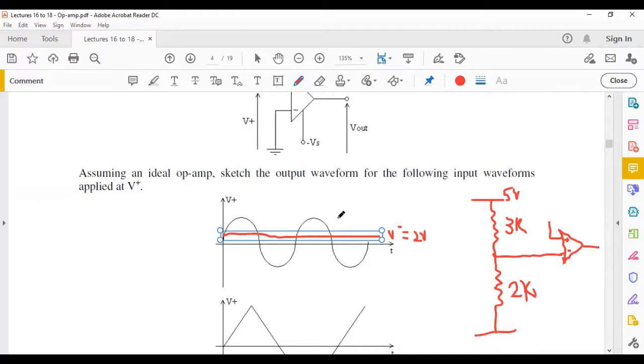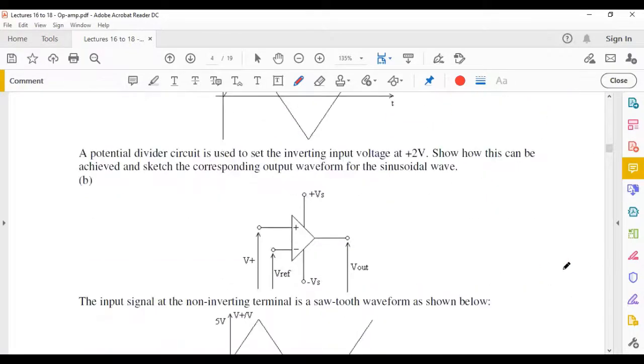This is used to control speed of motors. So as you move this line up and down, you are increasing or decreasing the amount of time that your signal is high or low. And typically this would accelerate or decelerate your motor. So it's called pulse width modulation. So in short form, abbreviation is PWM, pulse width modulation. So this is one method for controlling speed of motors.